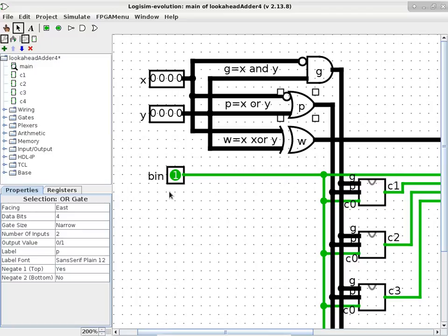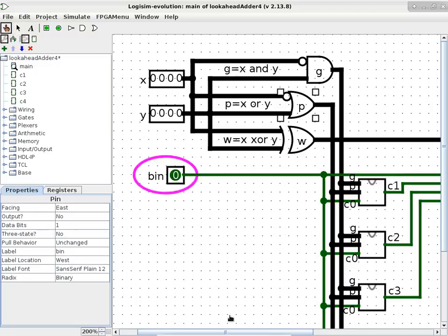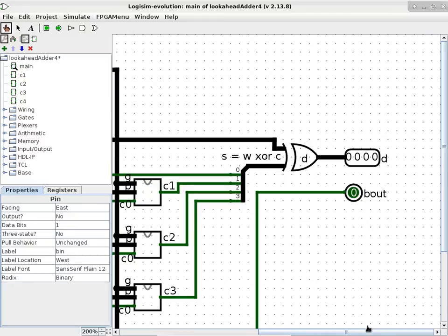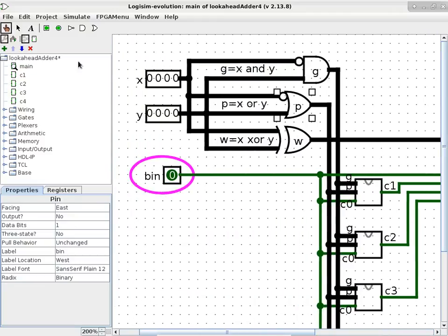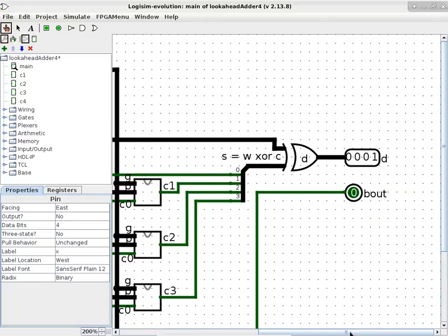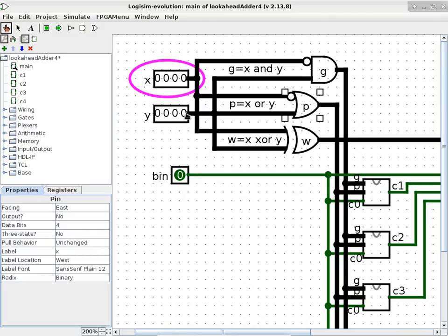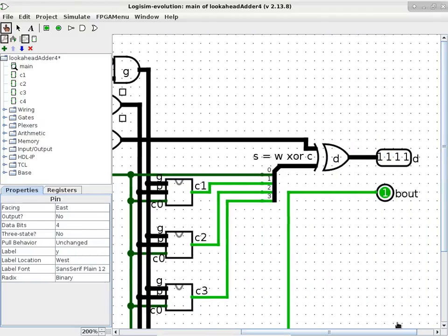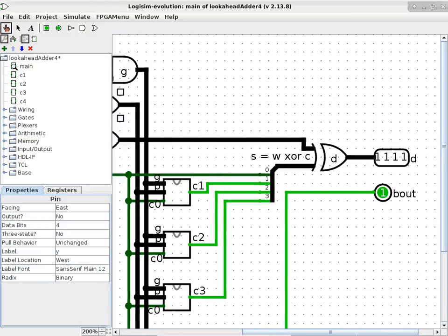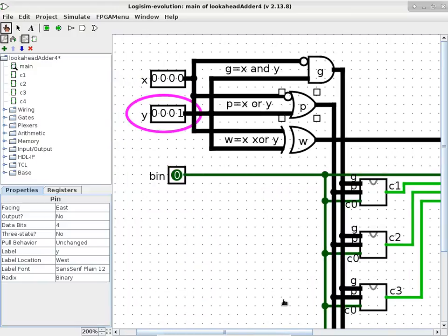All right, so the question is, is it working now? Well, obviously we have to test it. So the test is going to be all zeros, and then the output should be all zeros. That works, good. Then we have 1 minus 0 should be 1, right? Whatever minus 0 is, whatever that thing is. That's good. 0 minus 1 should be 1, 1, 1, 1 with a borrow. And it is 1, 1, 1, 1 with a borrow. So you can go ahead and check most of the other ones, but I think that should work just by negating the first input to the G and the P gates. Okay, that's it. That's the only difference between an adder and a subtractor from the functional perspective. The rest is just changing the labels and whatnot.